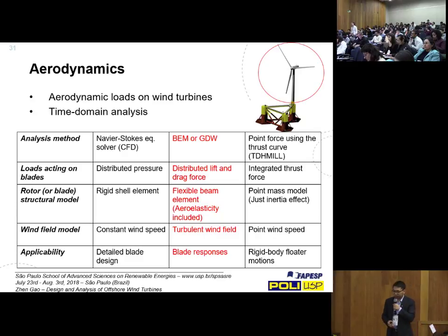and this can be considered with the flexibility of the blades and so on, so that also includes the elasticity. And in some cases, we also look at, say, the total thrust force acting on the floating wind turbine, and then the induced moment. So basically it induces the pitch motion of the platform. So that is just looking at the rigid body motion of the platform. We will mainly focus on this type of analysis.